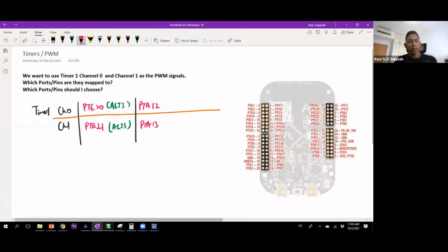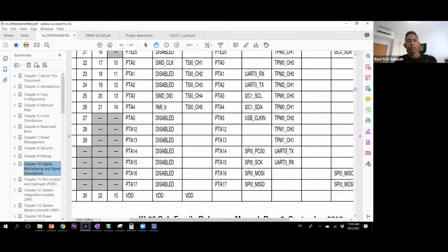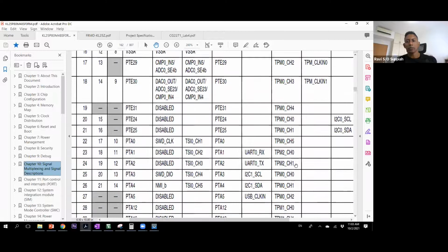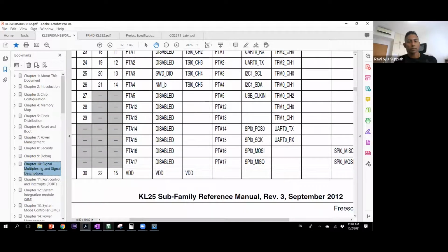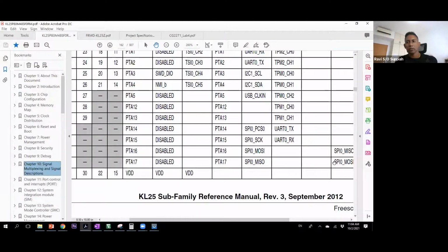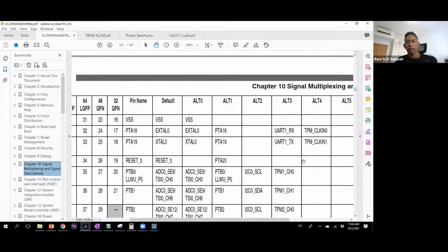And for that also, it is considered to be an alternate, just confirm, alternate 3 function. Yes, there is also an alternate 3 function here. This alternate 3, if you remember from your GPIO Studio, is to configure the pin, because each pin has various multiplexing options, so we need to select the correct alternate option depending on what we are using it for. Okay, so let's go down some more and see where else we can get it.